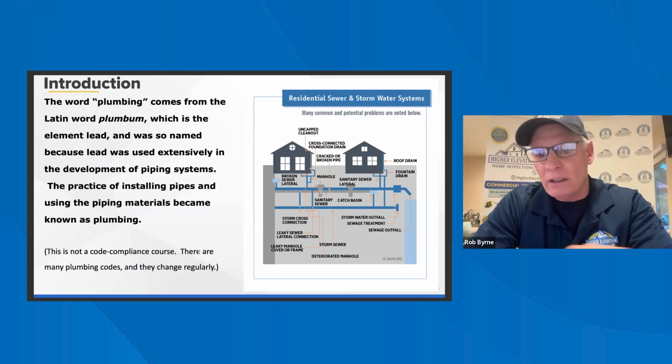Whether the water supply is public or private, that's important. The location of the main water supply shut off, so your clients know exactly where to shut the whole house off if there's ever a catastrophic failure.